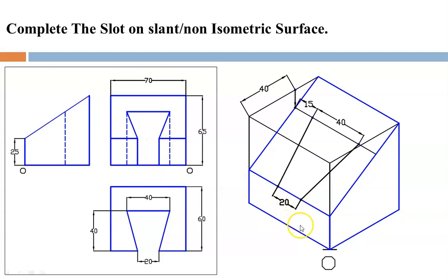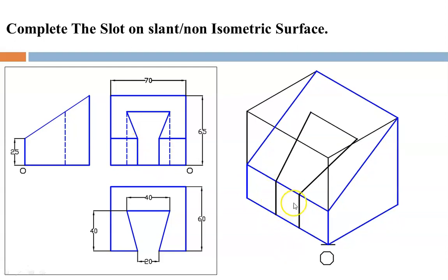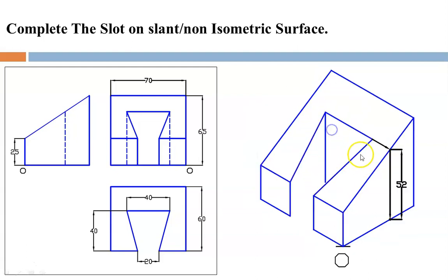From here one line and from here one line. You can see here these two lines appearing here, front view. Now we'll come to the depth of this, because one line from this corner is visible to you. The line from here is not visible to you, but up to what length we have to project it. So it will be calculated using this line. So I'll just project this over here, slant edge, and then I'll project it up to the base. So I'll get the height.